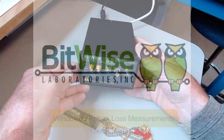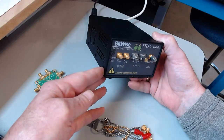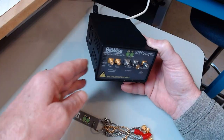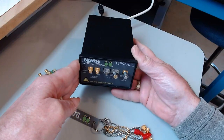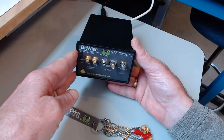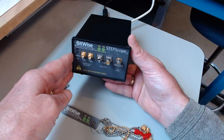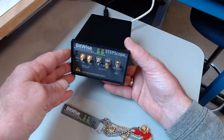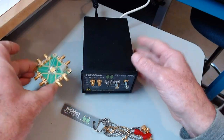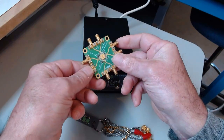Welcome. Today we're going to take a look at using the STEPScope to make better return loss measurements. Return loss is sometimes a challenging measurement to make, especially when you have huge discontinuities, which might happen when you are using 75 ohm DUTs and trying to measure them with 50 ohm systems, or when you have just a section of the response that you really want to use in your measurement.